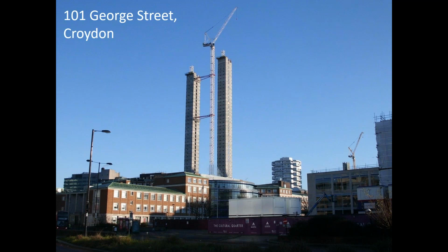When you're dealing with very slender structures, dynamics starts to come into play. And if you've got a slender concrete core attached to a steel crane, then a consideration potentially would be the natural frequency of the core compared to the natural frequency of the crane, checking for possible resonance.